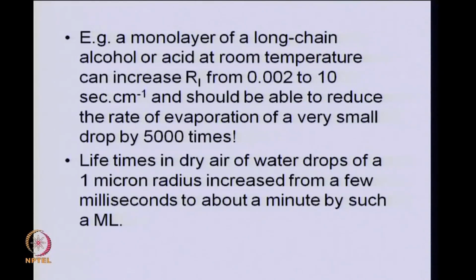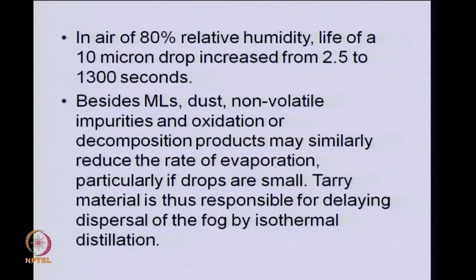Now, all it would take is very slight level of impurities present to form a monolayer, and you could witness a dramatic change in the time it takes for evaporating such fine droplets. Take another example, if air has about 80% relative humidity, then the life of a 10 microns drop will increase from about 2.5 seconds to 1300 seconds.